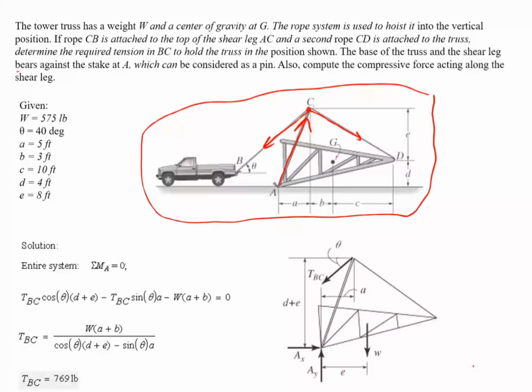You've got one known. Look, here we've got, what did I mention? I said you start your analysis inside the frame where you've got one known and a maximum of 2 unknowns. Now here I've got one known, that is BC, and I've got 2 unknowns. So if I do sum of all the forces along X, I will have the component of this one, and this one.